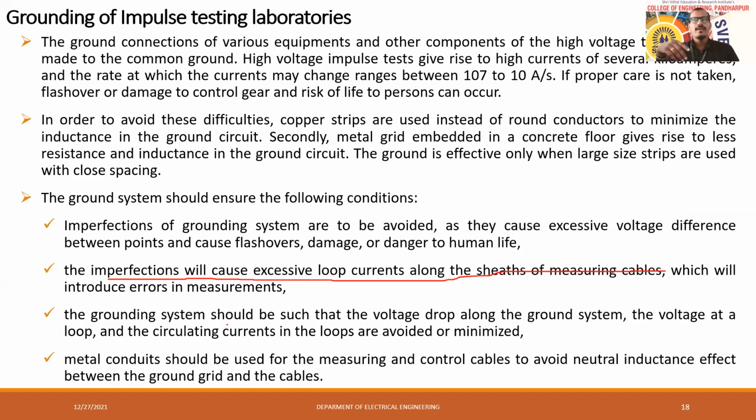Suppose we want to do an experiment at home, and we keep the wires bound together like that. If the wires are kept like that, as a bunch of wires, then every wire is carrying a current, and due to that the sheathing may get damaged, there may be some temperature rise, and there may be errors in the measurement. So that care we also need to take.